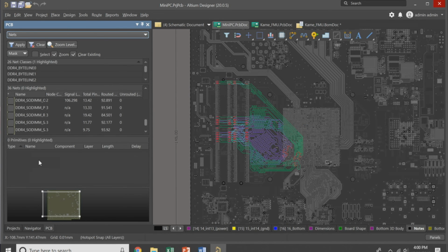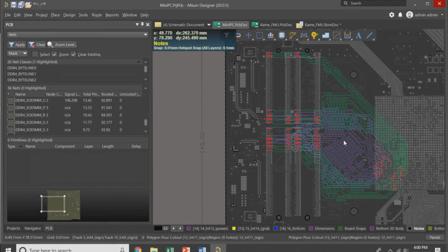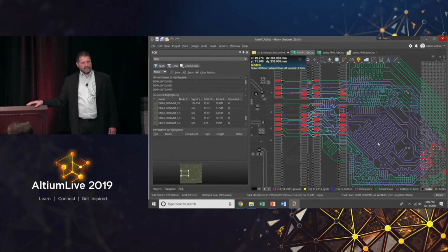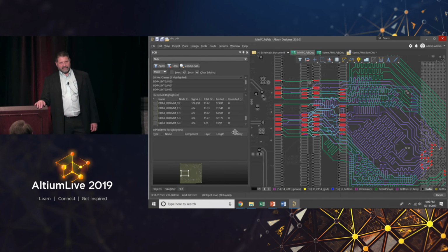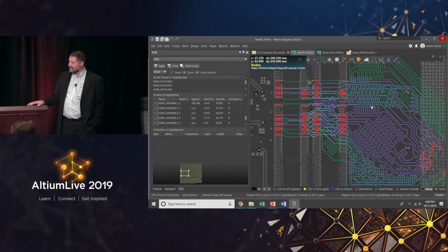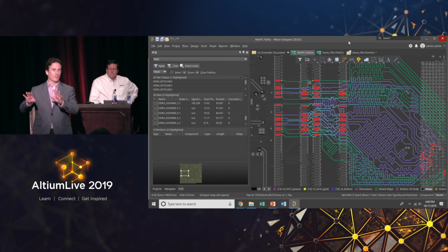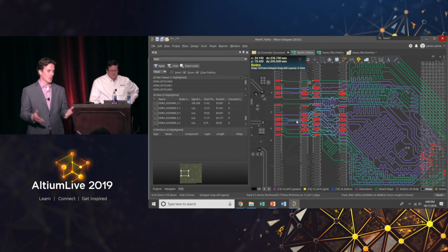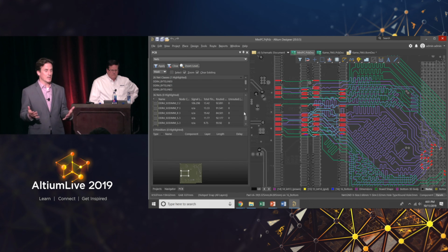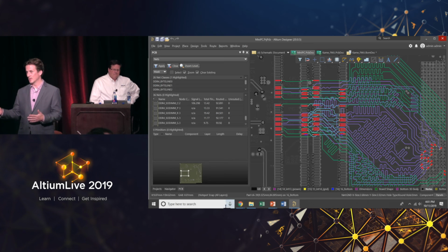Just to comment on reference designs, you should probably never use an IC company's reference design. They're terrible. I designed an RF board recently that did 100 dB better than the reference design. That's a huge amount. What I would say about the import process into Altium is it's a good starting point, and I'm not talking about the quality of the design you're importing, but in my experience importing a design to Altium gets me about 50% of the way there, and then I still have to do the rest. Starting point. You just said it.